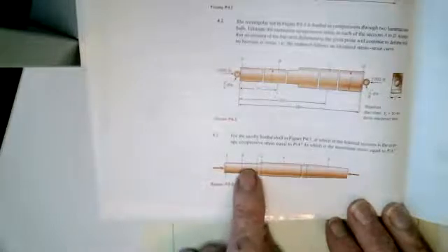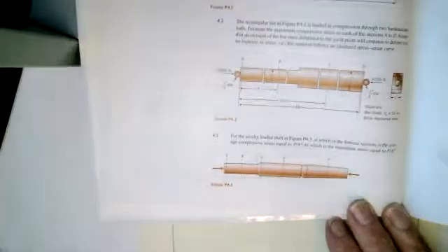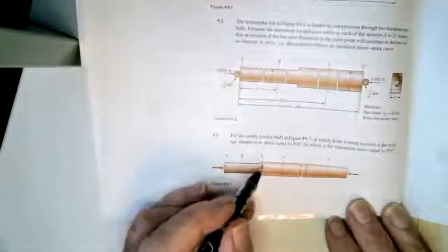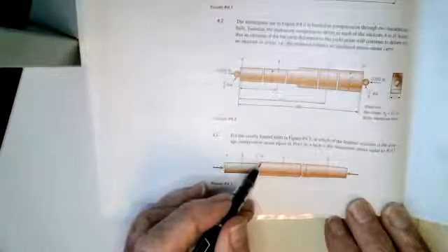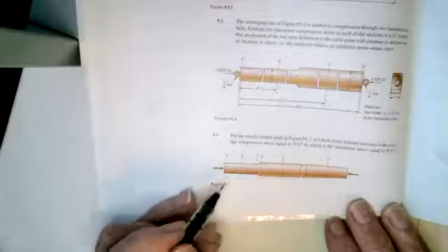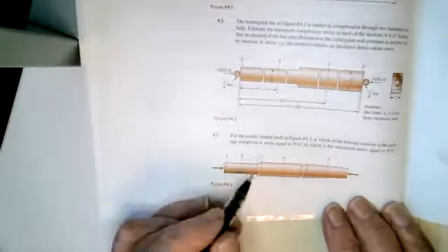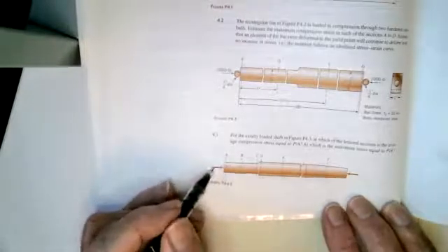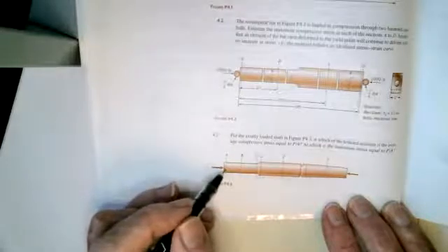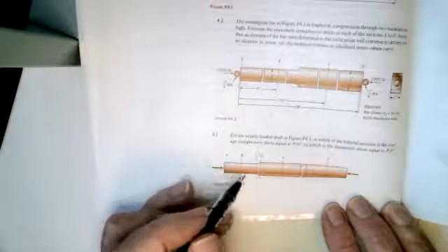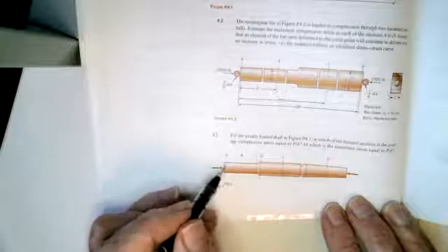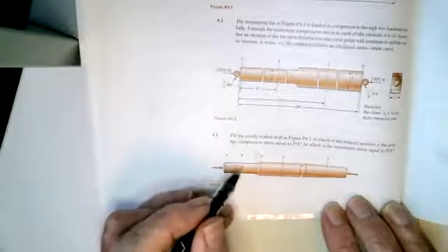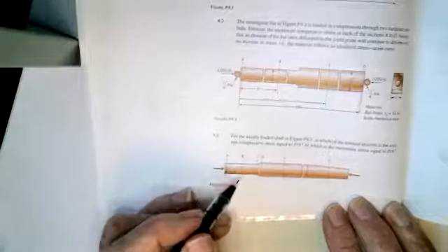If you start going near here, there's going to be a stress concentration. Here, the stresses will be bigger at the outside edge, and they'll be different down here in this corner. They tend to go to 0 in the corner. Okay, so it will not be uniform there. But here you're applying the load, and so there'll be a peak stress in the middle, and it'll be a lot bigger than P upon A. By the time you get about 2 diameters down, that stress distribution coming from this concentrated load will spread out. That's like St. Venant's principle.